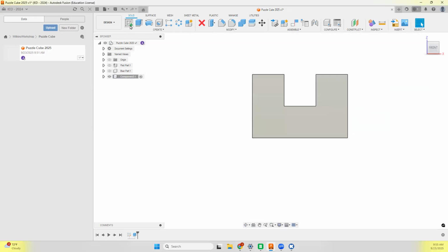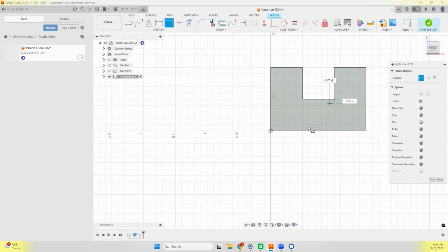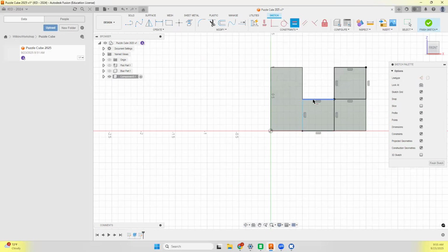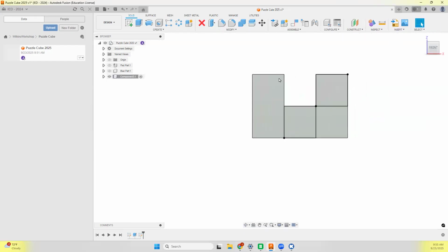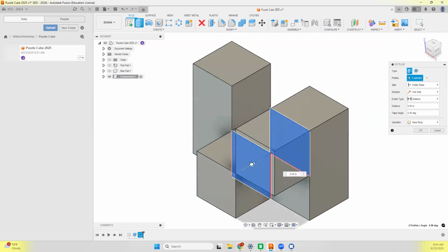0.5 for this. Do a new sketch on the surface. Again, a rectangle. We're going to go from here to here. And then this one goes from here to here. And we just want to say that these are collinear. Or you could do equals constraint. You could say this is equal to this, and that squares that up. Again, we're going to extrude these, pull this out 0.5.